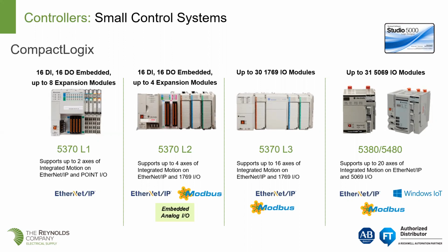And I guess one question here would be, hey, what about the SLC 500? We didn't include that here in our overview. SLC 500 is, of course, still an active product. It would be listed as active mature in Rockwell's definitions and their lifecycle policy, just meaning that yes, it is still around. It's been around since the 90s, but there is, of course, newer technology out there, such as the CompactLogix family here. So we wouldn't necessarily lead with an SLC 500 on projects unless there was a real good reason to do so.